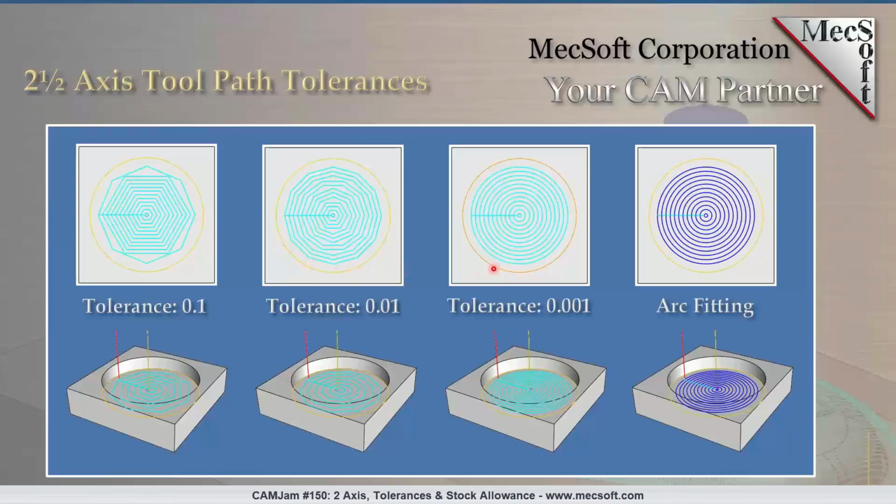With tighter tolerances, the chord segments will be much smaller and within the deviation of the tolerance that you specify. Now these affect more when you're using toolpaths outputting as linear segments, like when you're working with polylines or splines. When arcs are not being fit to your toolpaths, the tolerance has more effect, and as you can see there, there's more deviation from your part geometry.